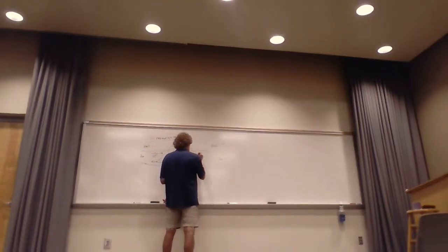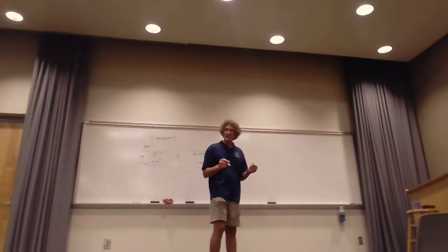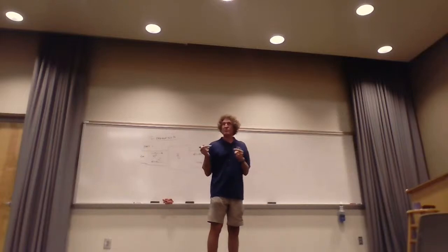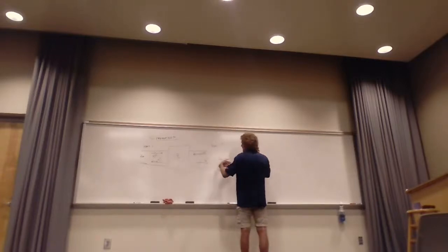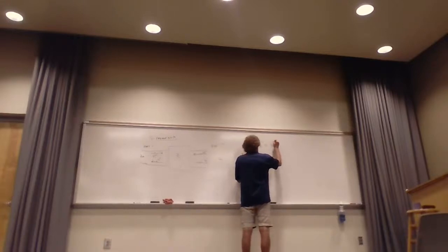Here, I'm also going to have a V2 plus, and I have a V2 minus. The minuses are always going away. All right? Pluses are always going towards that block there. Got it? Now, the relationship between the ports is the S parameters. And it says this, V1 minus is equal to V1 plus times S11.